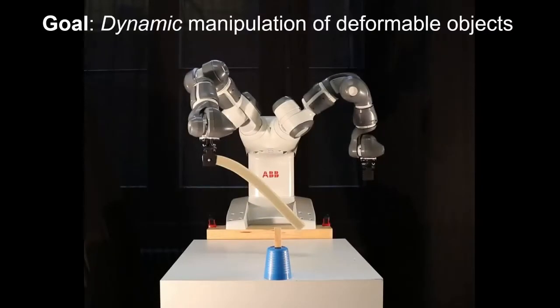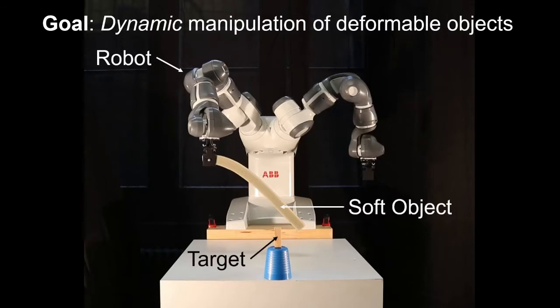To this end, we investigate how to leverage model-based trajectory optimization techniques for dynamic manipulation of deformable objects. In this work, we make use of a dual-armed Yumi robot and different types of elastic objects made out of foam. Our computational framework generates optimal nominal control trajectories in the robot's configuration space that can then be passed onto the physical platform. We test and analyze our implementation by experimenting with several tasks for the Yumi to carry out. For example, the goal here is to knock the wooden target off the table with one single swipe of the soft rod.